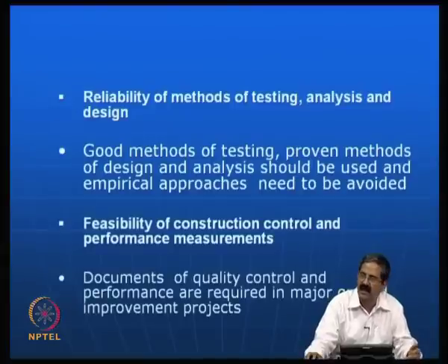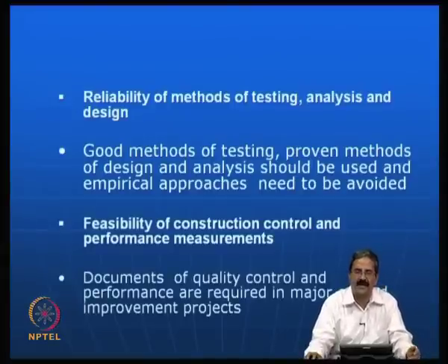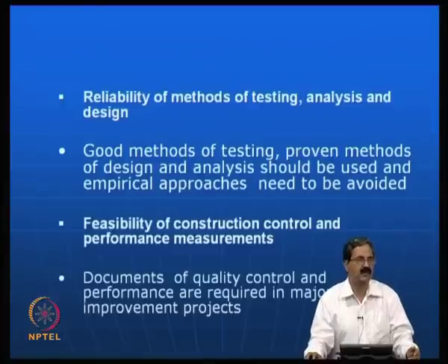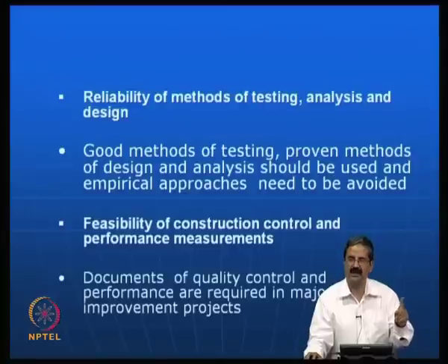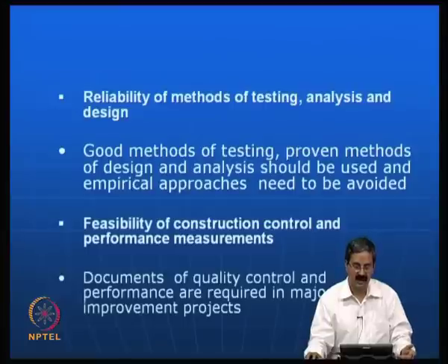Say, for example, I will tell you the classical example of an SPT. You have an SPT value, and then there is a connection to the phi value. You have one SPT test result, and you will get one phi value, and that equation that you are using is not specific to that area. It is an equation that is derived out of Japanese practice or an American practice. What you are doing is an SPT test in some place in India, and we do not know whether the same applies. There are so many uncertainties in the SPT test, because of the height of drop, the weight of the hammer, and so many issues. One should be very, very careful.